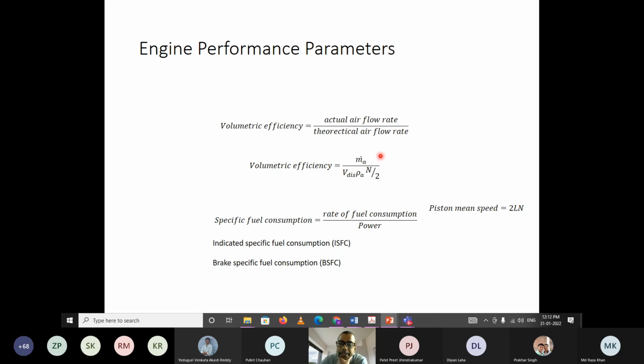We also discussed how we can measure the actual mass flow rate of the air in engine application. So all of you have suggested some methodologies. Yes, that can be used. As far as experiments in the laboratory are concerned, you have flexibility of space and you can use all sorts of equipment. But when you have to apply it on the engine, where space is one of the major constraints, packaging the whole system within the small volume is itself a big challenge.